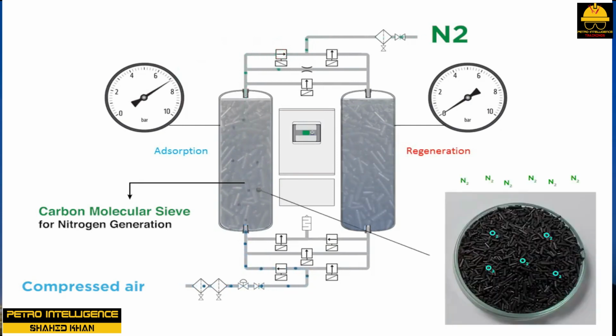The adsorption material can be activated alumina or charcoal or a variety of other adsorption materials. The adsorption material has selective properties that will remove specific components of the mixture as it passes over it. A stripping gas is used to remove the stripped components from the adsorption material.